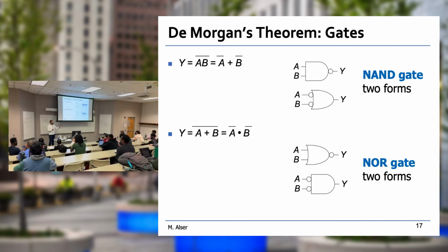Good luck. Now, if you look here, how many NOT gates do we need? Here, 1. Over here, 2, right? And that's the first thing to decide. If I ask you, you have only a single NOT gate to implement this equation, you look here, oh, come on, this really needs 2 NOT gates. How would I implement it using a single NOT? That's the thing you should deal with: how you push the bubble from the output to the input or from the input to the output.